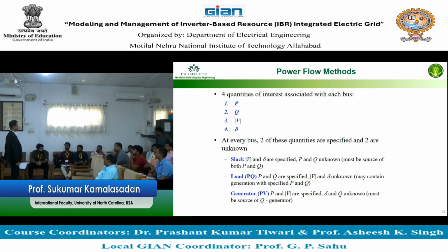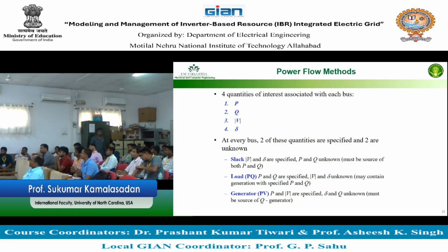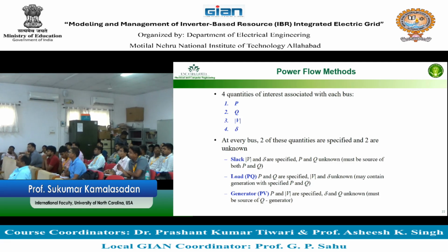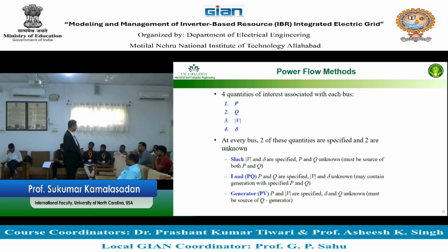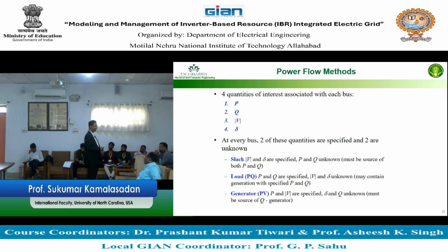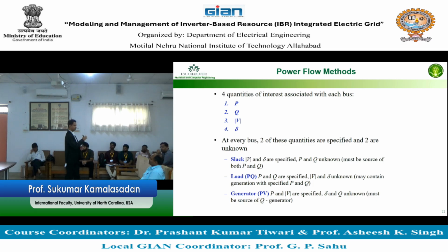Do I need to control the power on a bus that has no generator and no load? Do you have a bus with no generator and no load? Yes or no? Yes. So do I need to know some variable? Well, if you have a bus with no generation and no load, such a bus we call a pseudo bus, meaning power coming in and power going out. You can write the power balance equation. You don't need to do any math to do that.